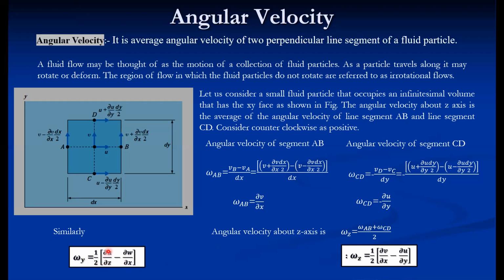This way we can estimate the normal velocity components. All these are the normal velocity gradients. This is not the velocity gradient along the same axis, it is along the perpendicular axis, so the same velocity components we can put in reverse manner. Similarly, for omega x, after x comes y, and then z. So after x, we write ∂y first, then ∂z, then the z component velocity we put here, that is w, and the y component velocity we put here, that is v.